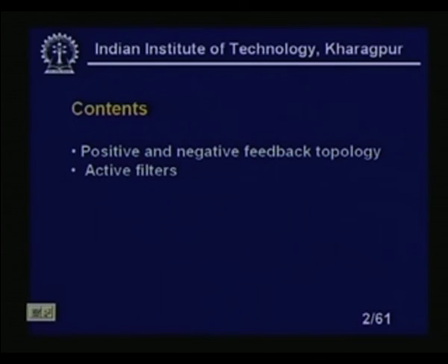We will discuss the active filters, single amplifier structure. It does not matter if the sensitivity parameters are high, because I have exactly designed the resistance value and capacitance value. So, even though sensitivities are high, I will get the desired value of the filter parameters omega p, Q p, omega z, Q z and capital K. It is very cheap and very small. Noise is also a concern, because if you increase the number of amplifiers, your noise probably will be predominant. So, these are the typical problems in the higher amplifier structures.